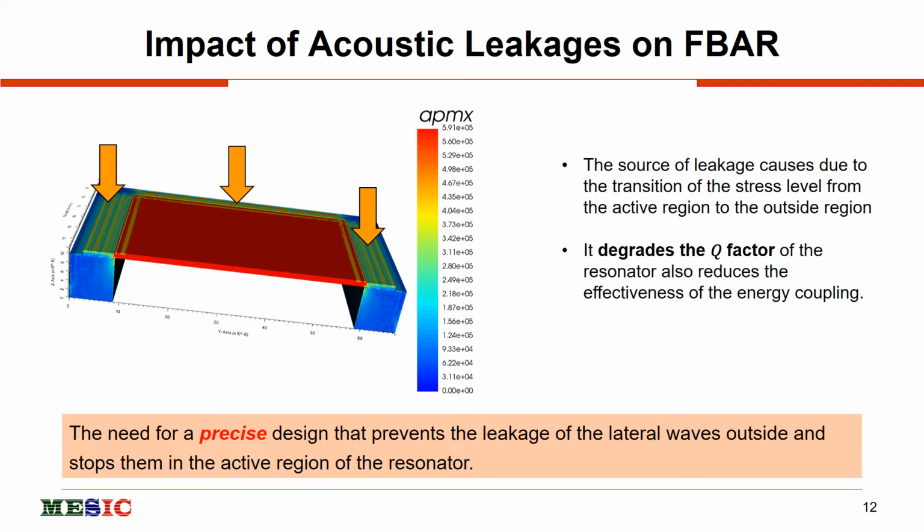This is considered an active region in which the piezoelectric is between the electrodes. So it degrades the quality factor. What happens is that when the leakage is more, it will minimize the quality factor and also the electromechanical coupling.